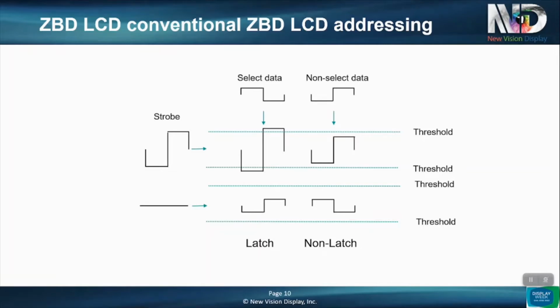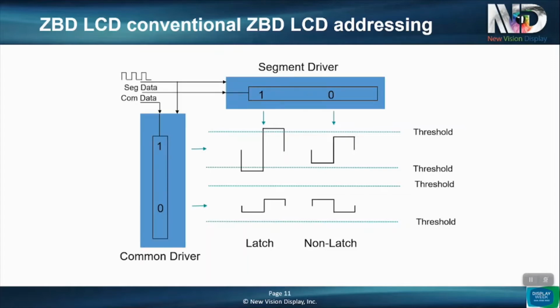We can implement this with a normal STN driver. The strobe becomes the COM, the data becomes the SEG, and we use a slightly different timing sequence compared to normal STN addressing, but the important thing is we use the same hardware.